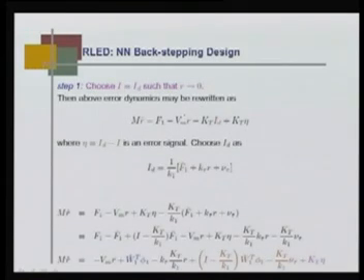So, the above dynamics may be written as M r dot is f1 minus V_m r, and now I represent this differently. Earlier it was simply minus k_t i. Instead I write i_d plus k_t eta, where eta is i_d minus i. You can easily see this is the same as my original dynamics, f1 minus V_m r minus k_t i, which I am representing in this particular form.